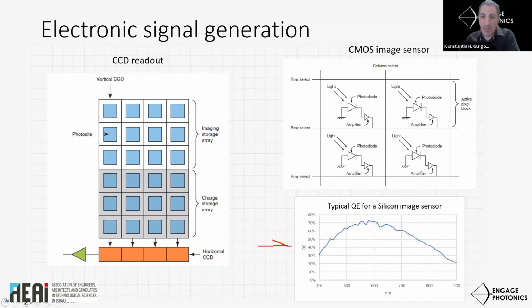Image sensors carry out the exposure differently. Global shutter CMOS sensors and CCDs expose the whole array simultaneously, while rolling shutter CMOS image sensors apply a different scheme. We don't have the time to talk about everything, but while the pixels are being read out, image sensors employ different approaches to prevent incident photons from generating unwanted signal.